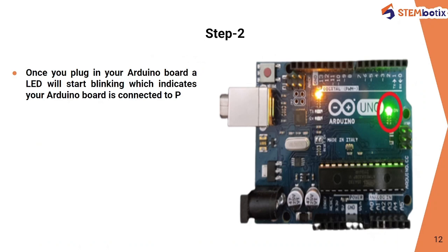Once you plug in your Arduino board, the power LED, which indicates whether power is going through the microcontroller board or not, will start blinking. Here we can see the LED start blinking, which means your Arduino board is successfully connected to your PC.